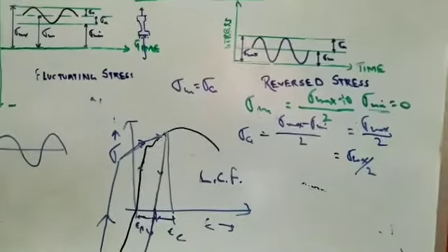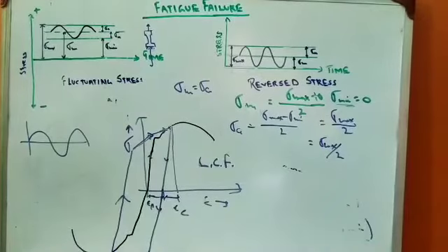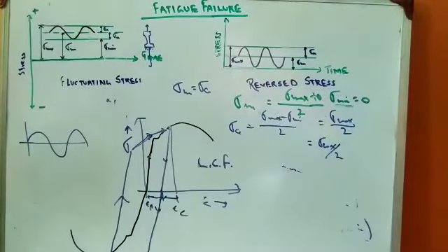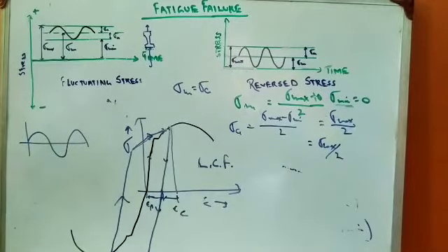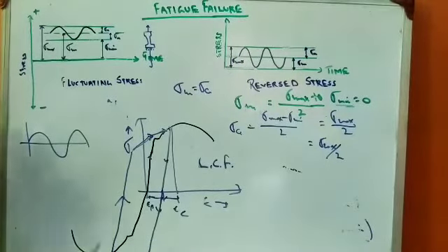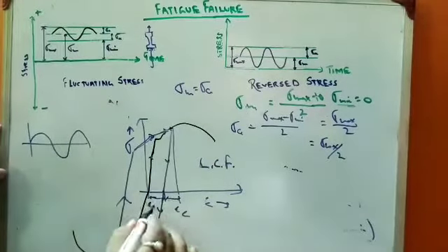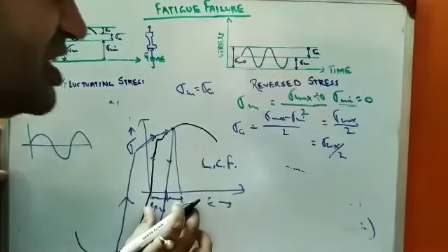Now basically what happens, this low cycle fatigue or high strain fatigue is designed on the basis of strain, strain based design. Why strain based design? Because if you observe from this point to this point, the variation of stress is very less, but from this point to this point, the variation of strain is very much.